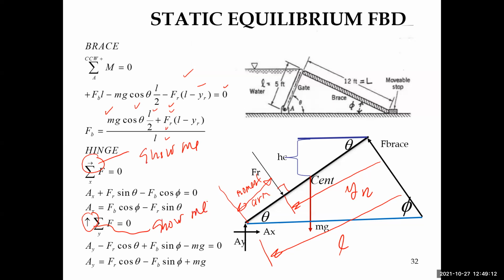So I need for you to show me that you understand that I must have an assumed coordinate system, an assumed plus direction and minus direction, and to indicate so on your summation sign, because a problem can be, as you can perhaps see, a number of pages long, and you must be able to carry that through from step to step. So the summation of forces in the X direction is 0.